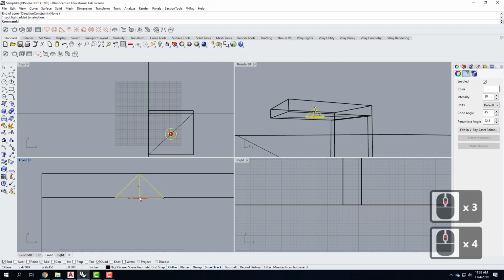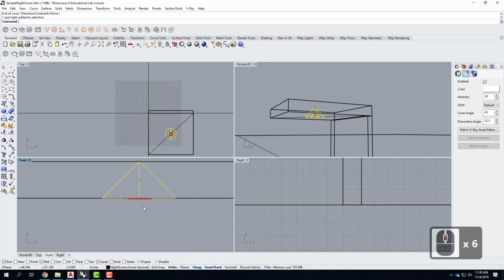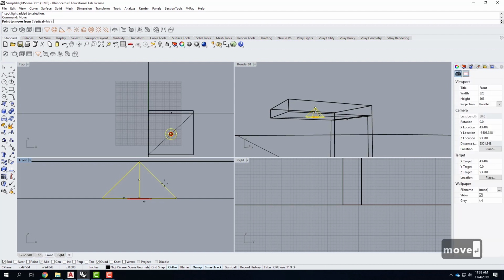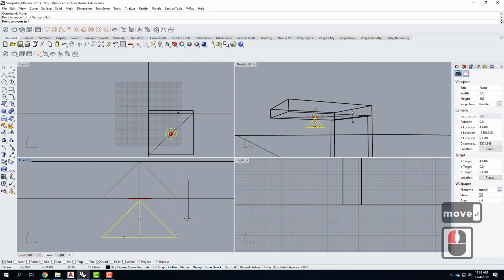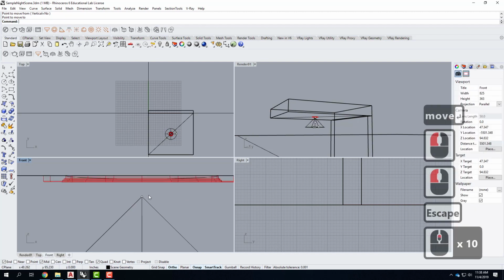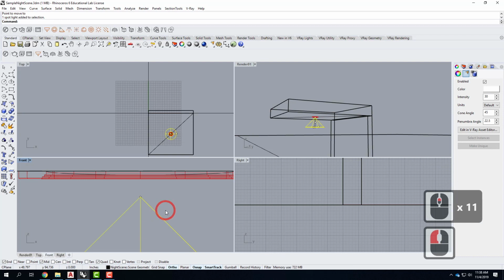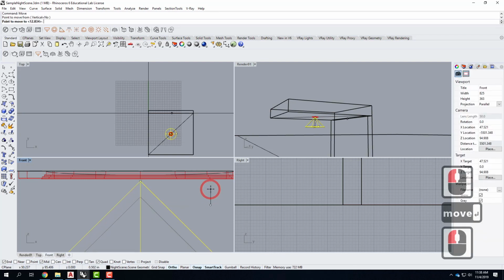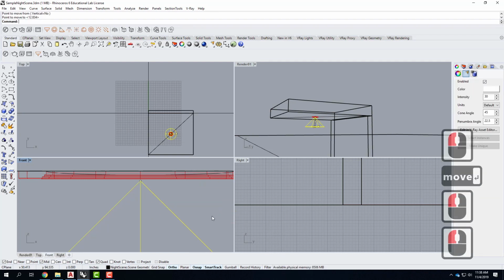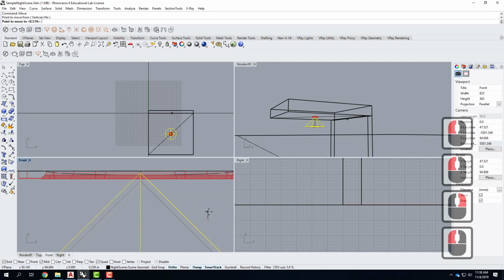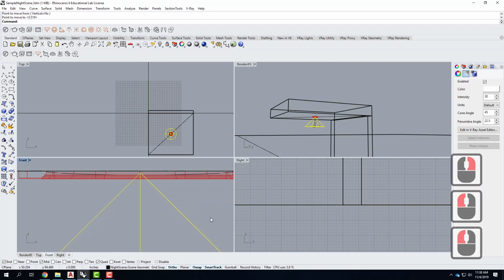There's a few rules for this light. Number one, the origin of the light, so this point up here, can't be intersecting or contained within any objects. So I need to move it down so that it's below all my geometry. So you see it doesn't actually interfere with any of my geometry. I can move it to be really, really close to my geometry, but it can't be there, where it's inside, because then this light would be shining on the inside of my light fixture.